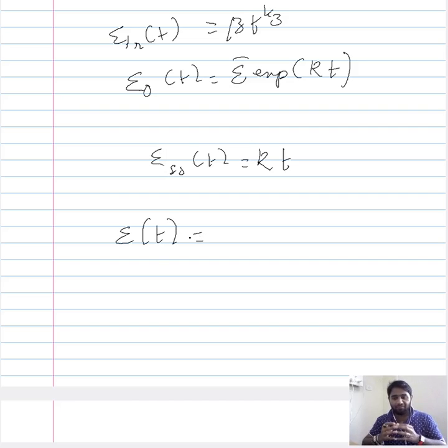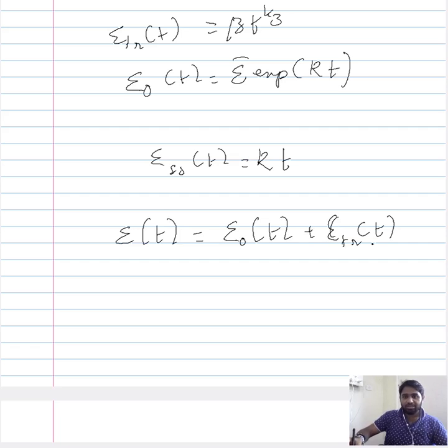So you can have an expression for strain over a period of time, which now includes the instantaneous creep, which is independent of time, and you have your expression for the transient creep, which belongs to the time development zone, and steady state creep, which also belongs to the time development zone.